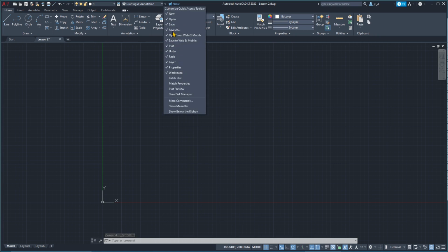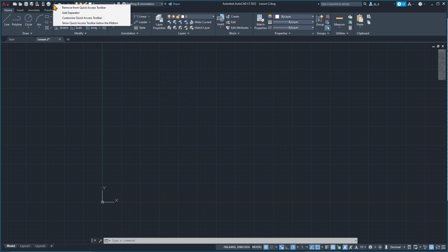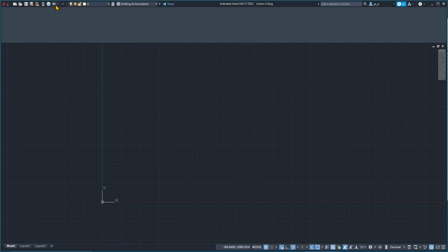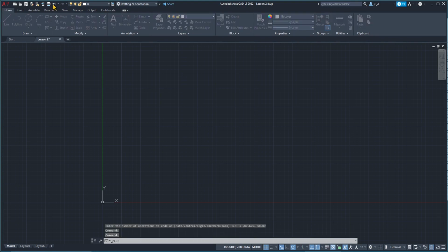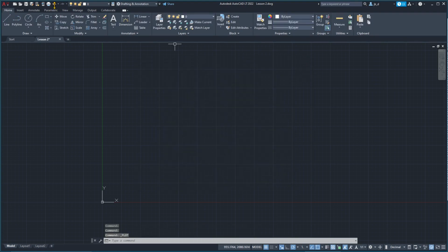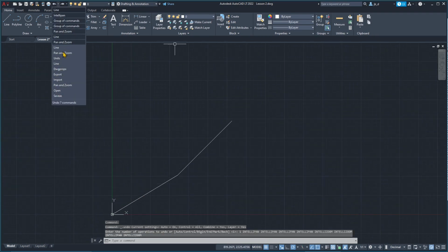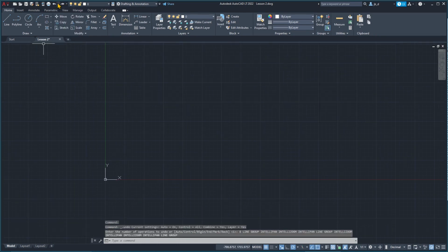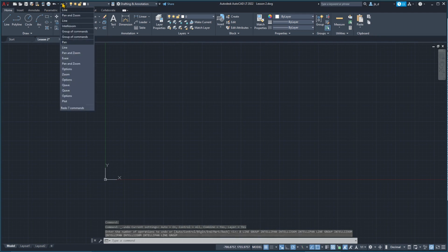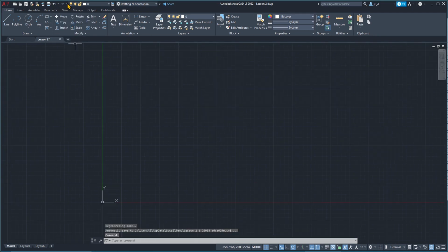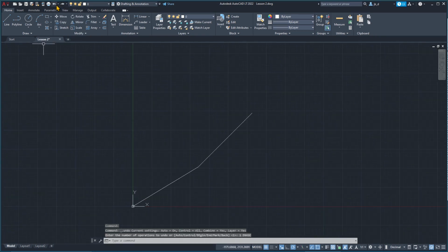Look for the one that we just inserted, which is not visible, so let's just right click and remove it like that. Remember also these two are really important to undo and redo your actions, and be careful on where you click. And also this is going to give you a brief history of what you've done in terms of navigation, pan and zoom, and creating lines. So you can click and go to a precise point in the history, going backward, and the same also going forward. So maybe I want to just go a little bit back here where I created my lines.